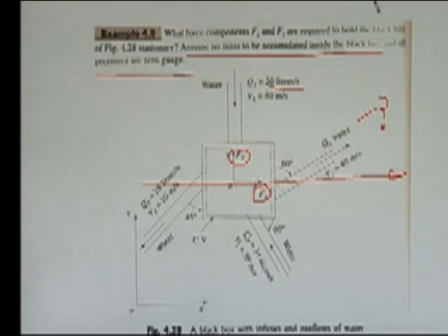So, with the help of Reynolds transport theorem, the rate of change of property of the system is equal to these three. The first term will be 0 because flow is steady, minus B in means momentum going inside the control volume in x direction. This is x direction and this one is y direction.